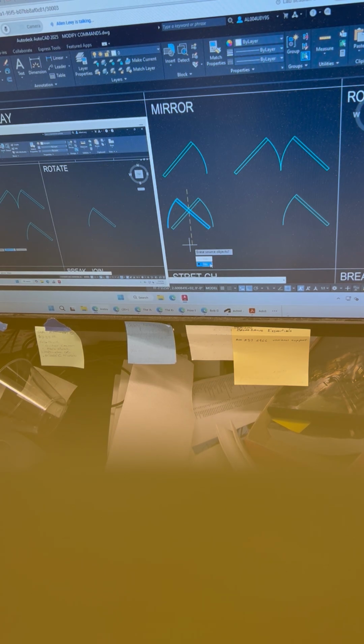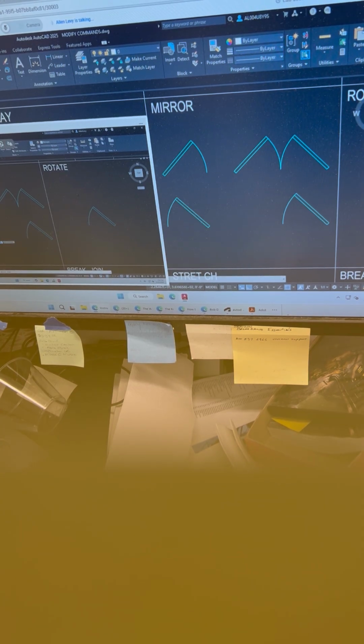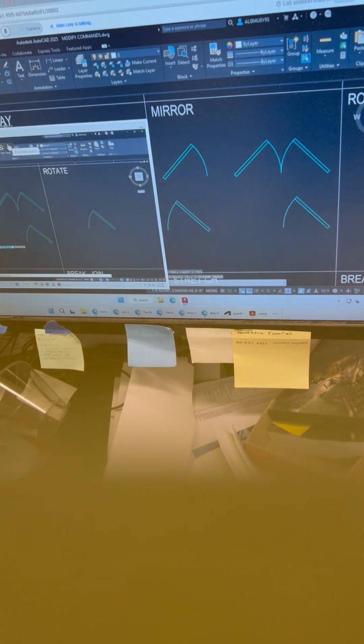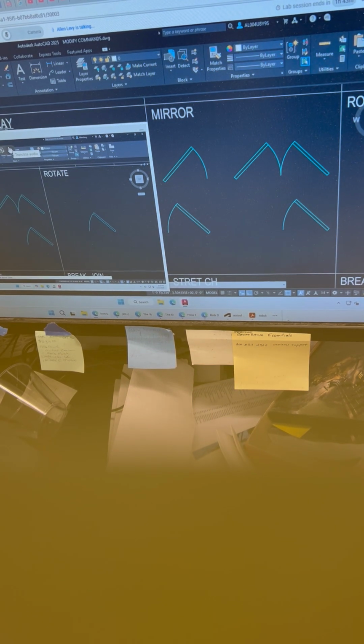Try this, and I'm not going to be exact about this, but if you just sort of pick a point in between the end of the arc and the hinge point, like right about here in the middle, go ahead and pick a point and move your mouse straight up or straight down. Notice how it shows a mirror image mirrored along that mirror line. Now try this. Move your mouse to the left or right. Look how you can mirror it that way. So the mirror line is the reflection line, the line about which everything mirrors.